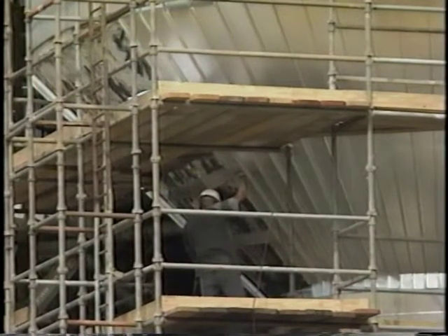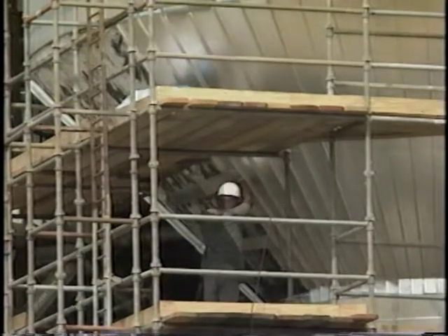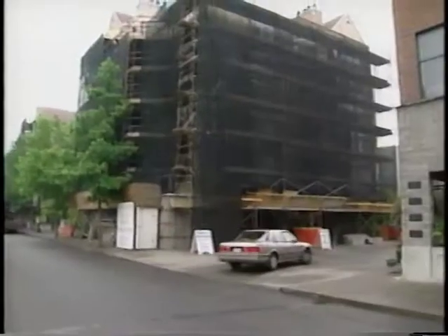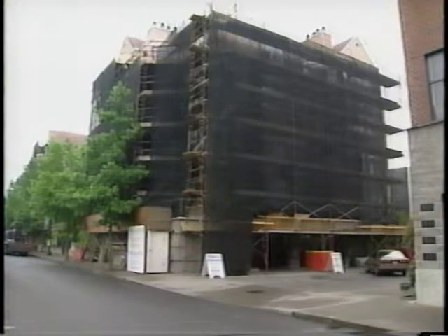Toe boards of at least 1.5 inches must be installed on all open sides of the platform. If tools or other items next to the edge are stacked higher than the toe board, then mesh, debris nets, canopies, or other sufficient means of protection must be installed.